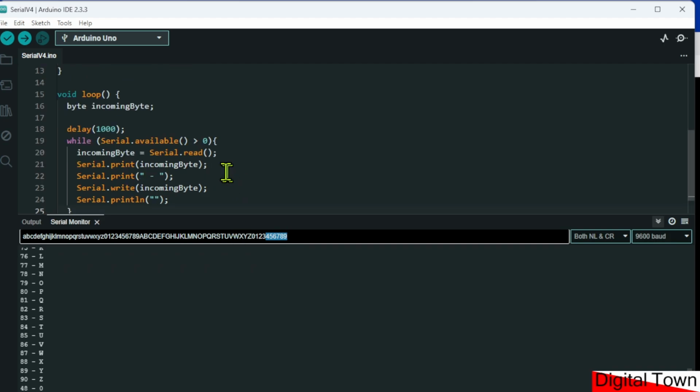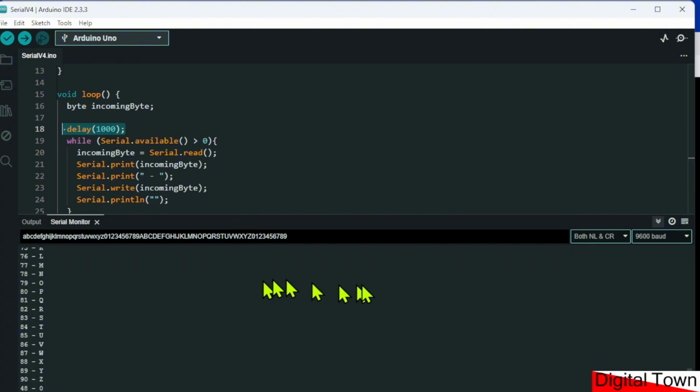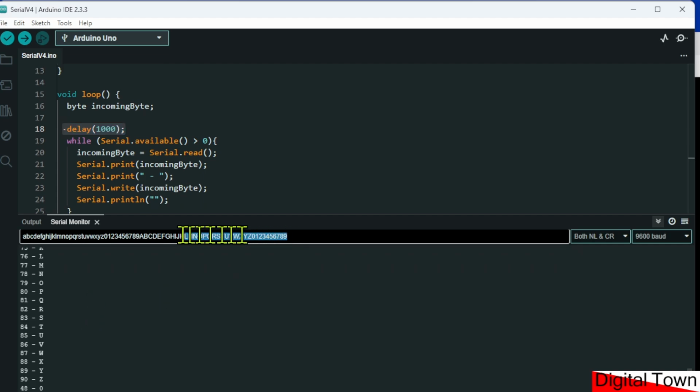That's because during the delay period, data was still being transmitted in towards the buffer. The buffer no longer had any space for it. It can't send the data back, so it just loses it. So if you overload your inbound buffer, your read buffer, the danger is not that your code will get blocked by the waiting period. What you're actually going to lose is the data that you are transmitting.